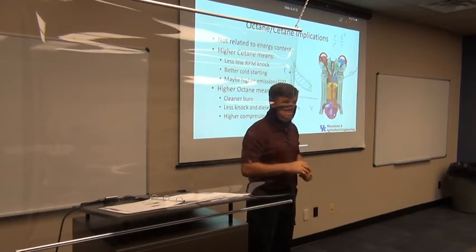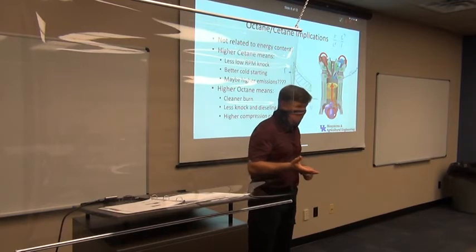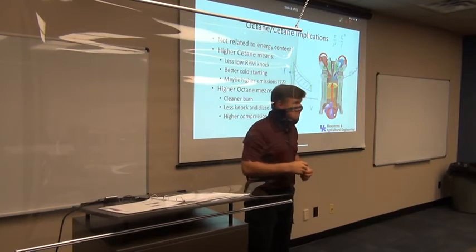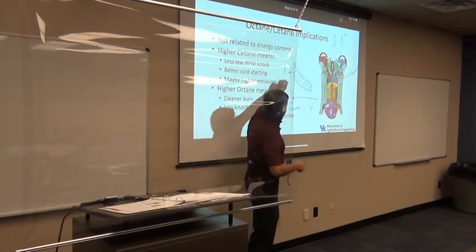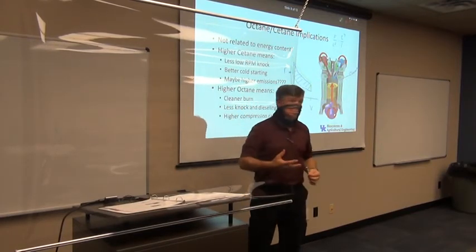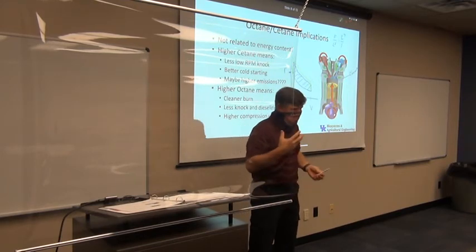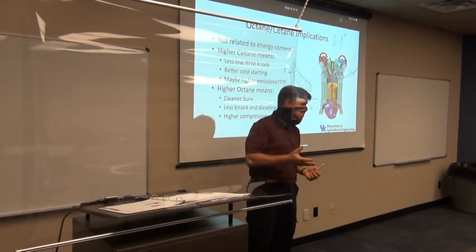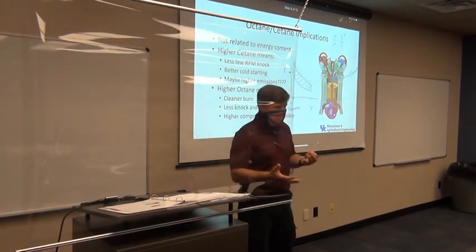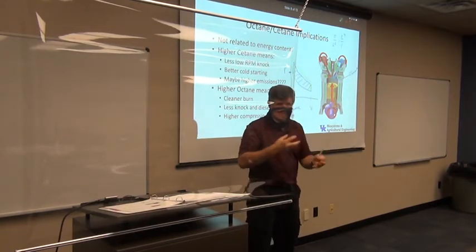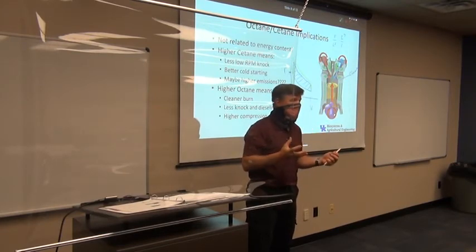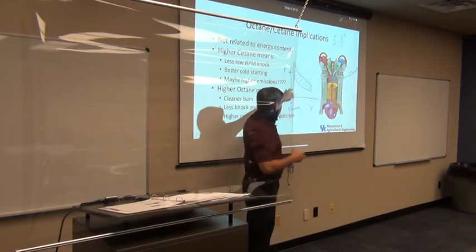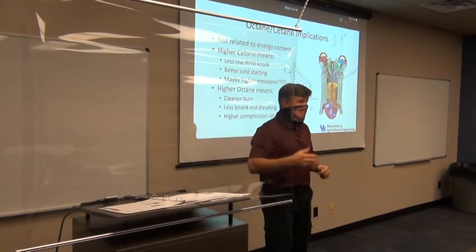Now, if I have an engine that calls for it, and you have higher end vehicles, like some of the higher end Mercedes, those vehicles will actually require higher octane fuel. What they're doing is they have more compression ratio in the engine, so their engine is ready to do it. And they're doing some other things as well. It's not just as simple as compression ratio. They're doing some other things with air fuel ratios, because they're burning it at higher pressures. They actually are affecting the pressure inside the cylinders. There's a lot going on that they can utilize that higher octane fuel to be able to get more power out of it.